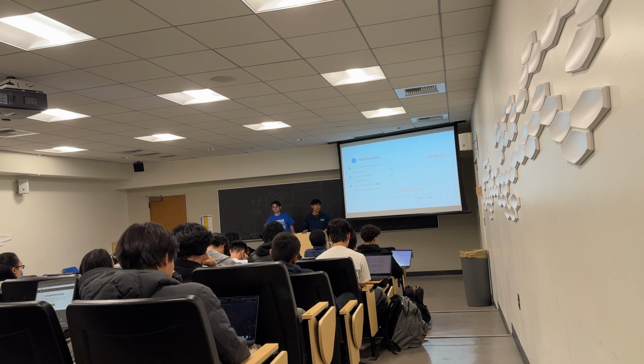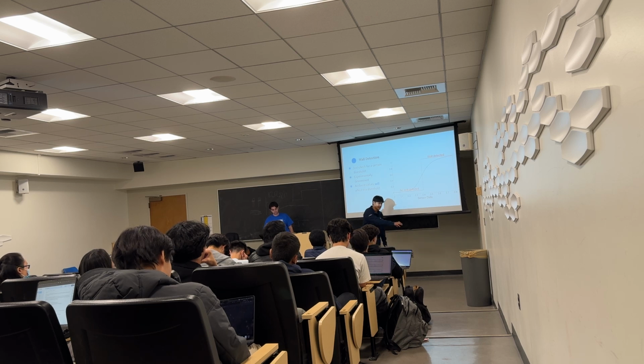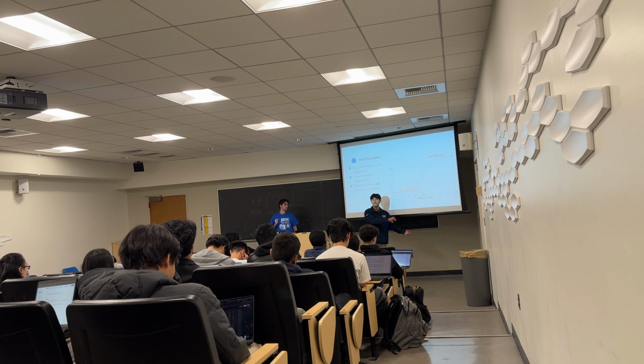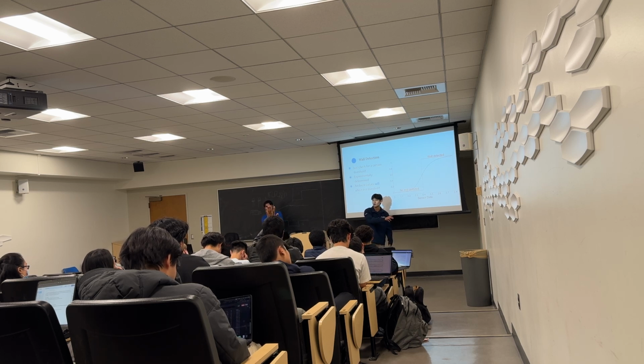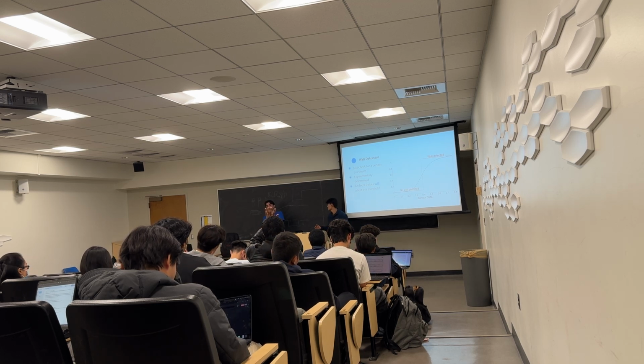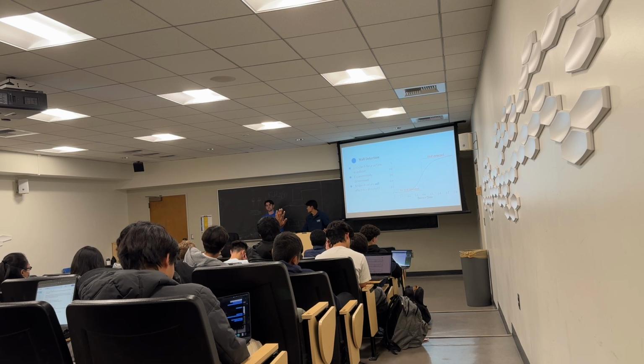So we'll talk about that, but essentially you're going to be placing your mouse a given distance away from the wall, turning on your IR emitters and receivers, and seeing what values you get at that exact location. You're setting it at the exact distance you want to turn at. If you're asking for precise distance measurements, you're not going to do that, because these sensors are not accurate enough to be really reliable.